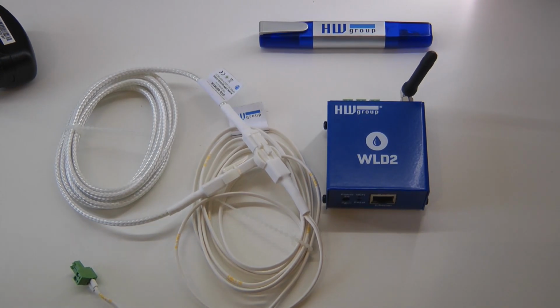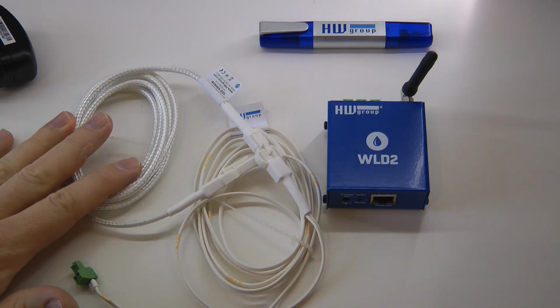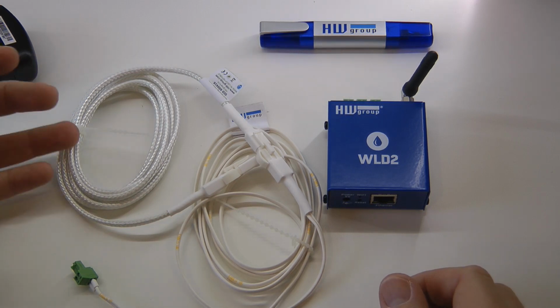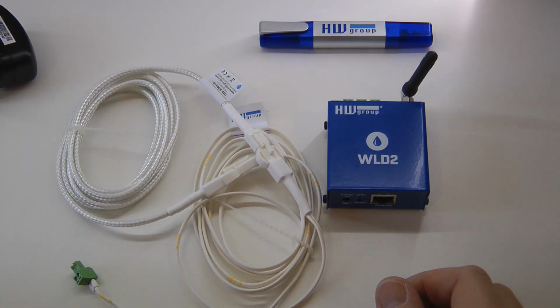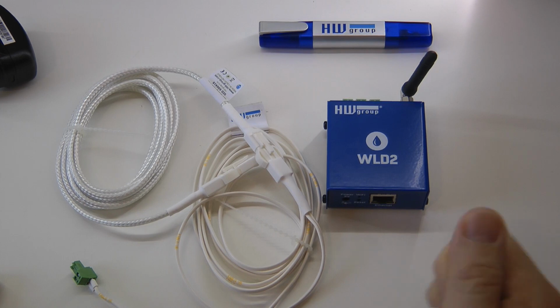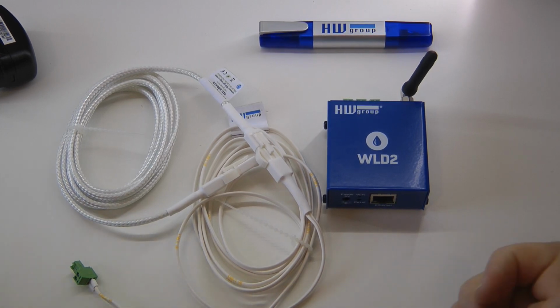You set up your email list notifications or your phone numbers, and your maintenance person would get an email immediately once water is detected. And of course, if you don't respond to that email, and there is still water detected, let's say after 10 minutes or after half an hour, you can configure the system to send you an additional notification, just to make sure that you're not forgetting about the fact that maybe your server room is being flooded.